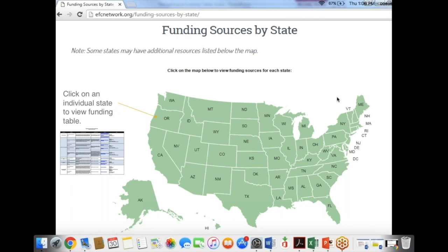So for them, a really good starting place was, let's go out and figure out which valves turn which direction. You know, where are the valves, how many turns does it take, what direction do they go? And then they painted the inside of the valve can lid a certain color. So if it was turning to the right, it was one color. If it turned to the left, it was another color. So you can imagine how much time and effort you're going to save by having that information now available to you. So they had an inventory, they had a map, and then they had these painted valve cans.